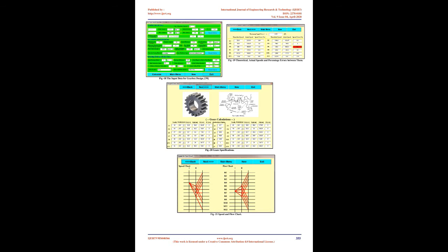Actual speeds are produced in the spindle of machines due to the motor speed and the mechanical movement of the meshed gears. Actual speeds are calculated by the motor speed, belt pulley reduction ratio and the designed gears using the speed chart. Theoretical speed can be obtained from standard tables. Some approximation in design processes must be less than permissible errors, all can be calculated as follows. 23, and it is an approximate value of the actual speed.